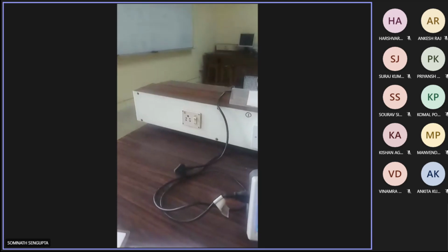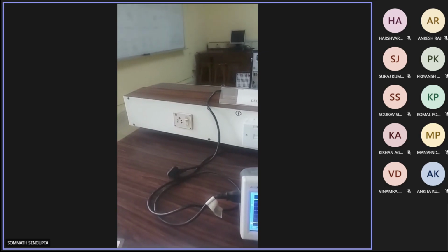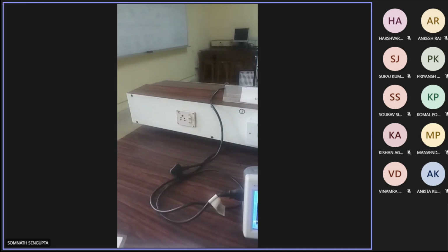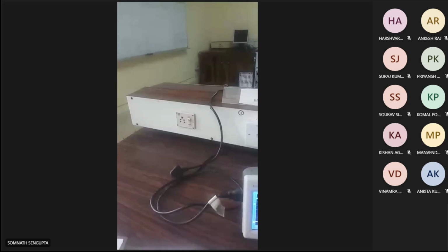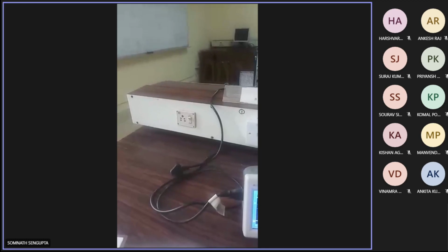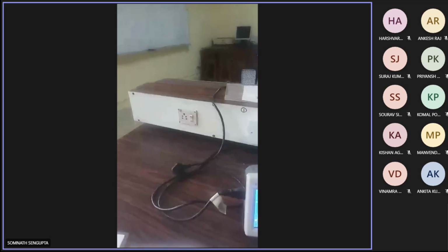In the first stage there is an RC integrator. What does it do? It receives the Manchester coded data in square wave form, and it gives you a waveform like a triangular wave.